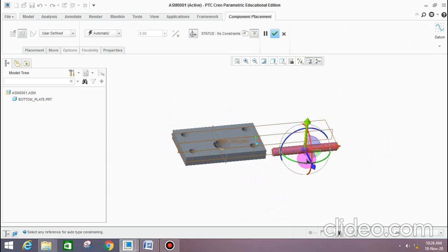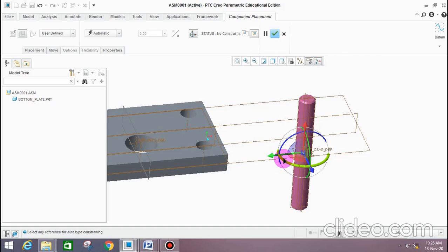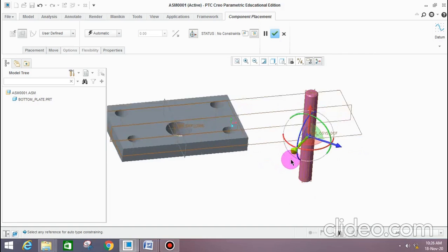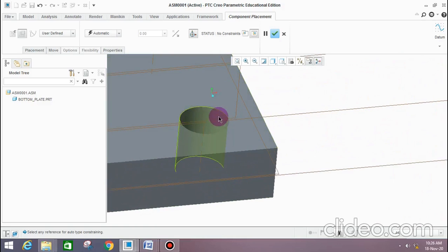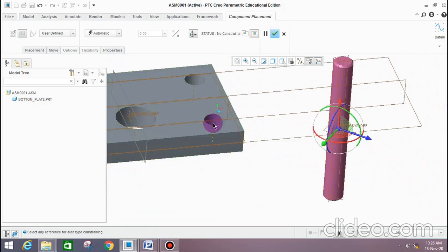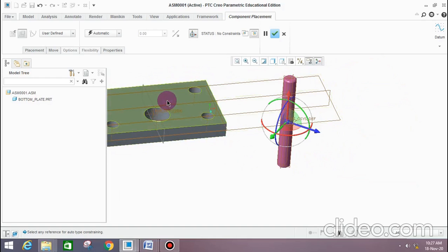Here, so this is the 3D dragger, it can rotate 360 degrees. You are arranging your adjustment. So here one hole, in this hole we observe one axis. Similarly the guide pillar also has one axis. You should make both the axes coincident, so this object has degrees of freedom 0, otherwise it is movable. So we have to assign this circle axis to the guide pillar axis.